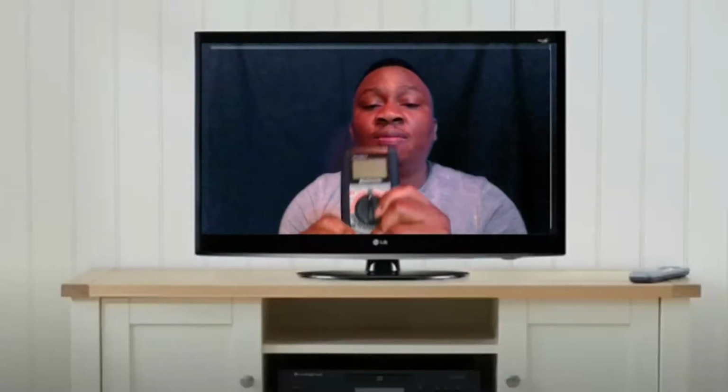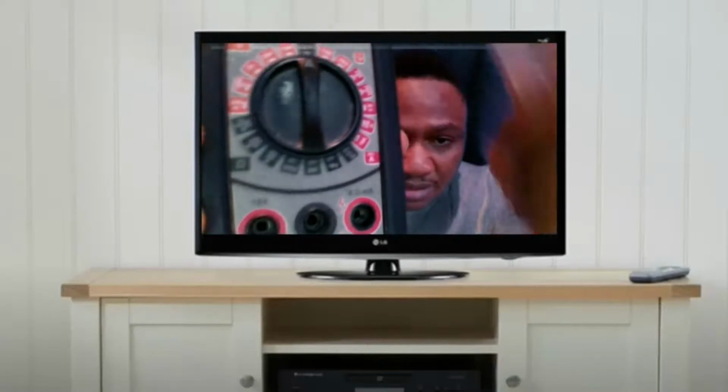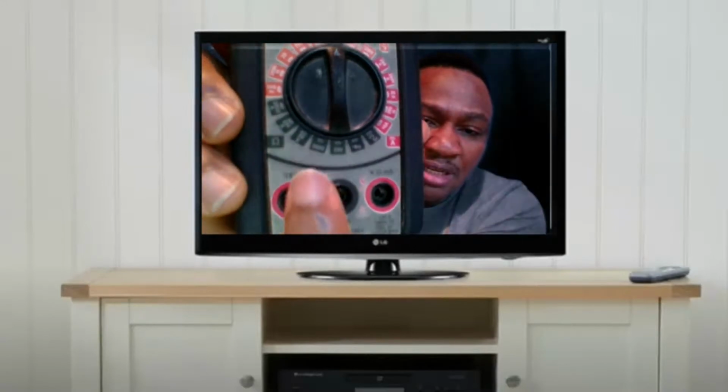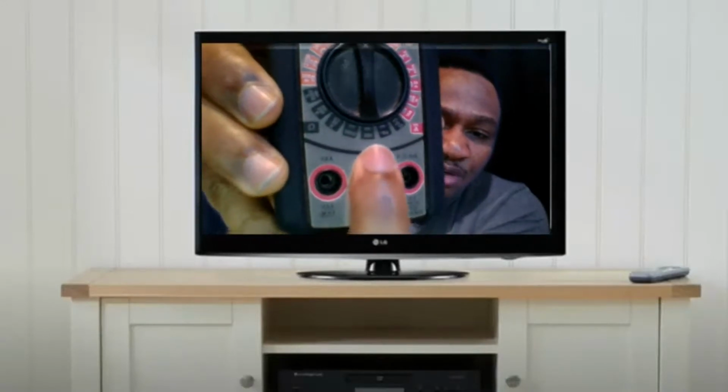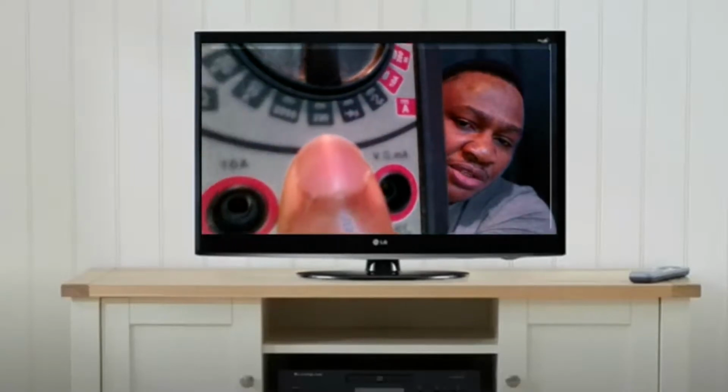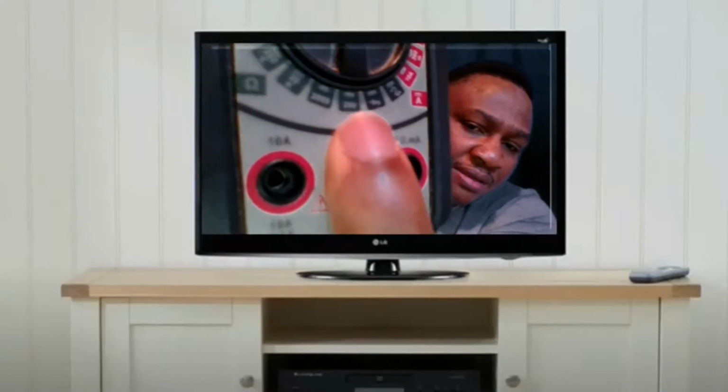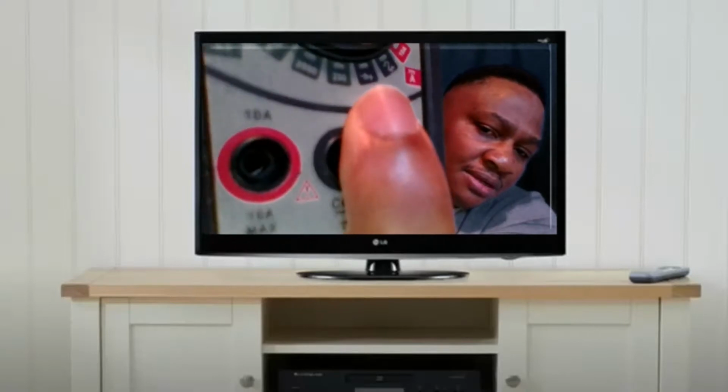So this is my digital meter, one of my digital meters, and I have a filter on the background, so it's affecting the colors here. But let's see. If you want to use this to read your transistors, you want to be looking at the diode range. Okay, can you see that? The diode range. That's what you select when you want to read the transistor.